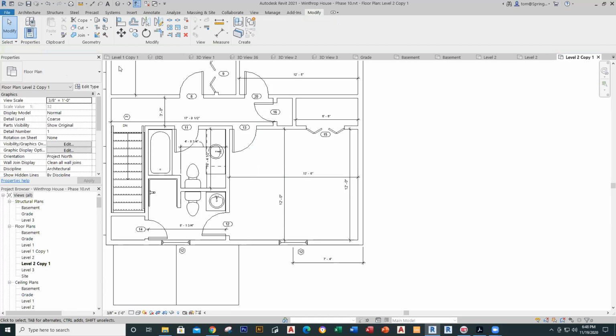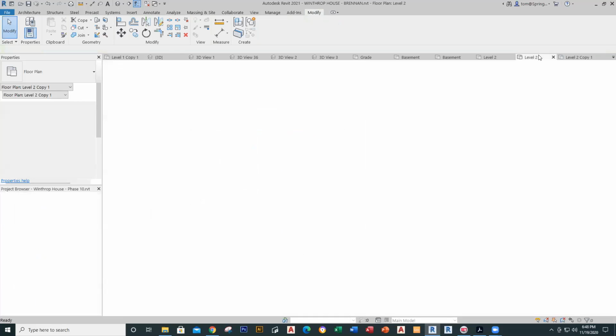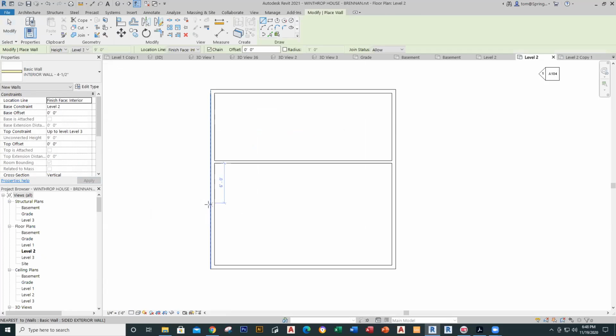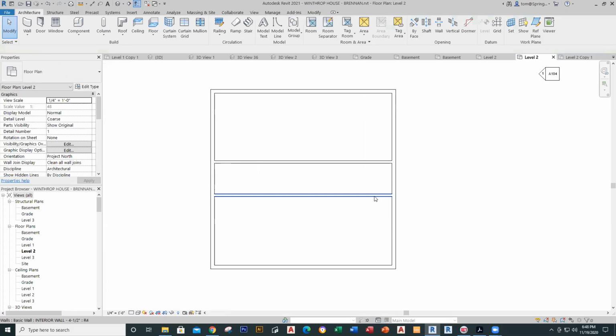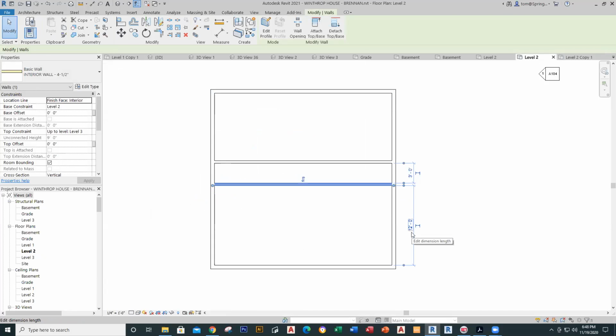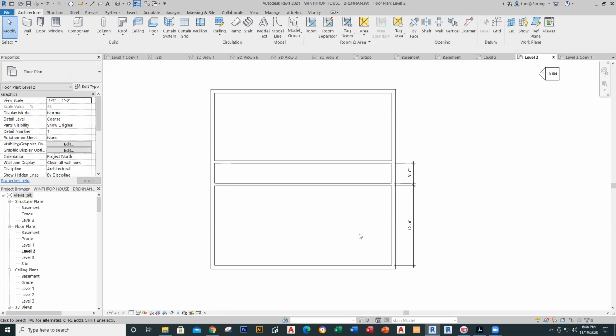So we'll do that one now, and we'll go back to that and make that 12 feet. We'll go to my wall, architectural, and I'll place this. I'm going to click on it here and make this one 12 feet. Like that, boom, and this is 3 feet now, which is exactly what it should be. So that's 12 feet. I can save that and make that 3 feet, boom, and we are good to go. I've got those in place, and that's the basics for the walls for the second floor.